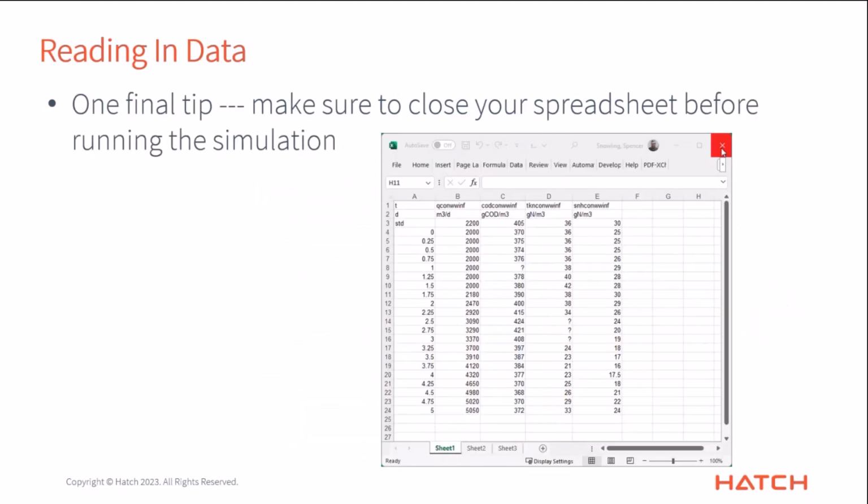One last thing I will mention when you're using these spreadsheets and changing and editing your data: make sure you close the spreadsheet before you start the simulation, before you hit the start button. If you have this open, GPSX cannot read this file. It's the same way that you can't copy or rename your file if you have it open. GPSX also cannot read it.